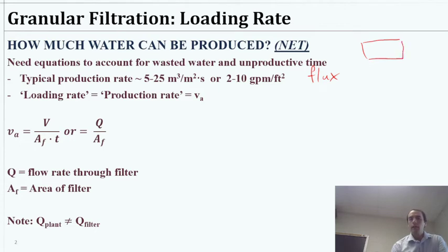So I'll say the plane of the surface of the filter bed. So a two-dimensional plane. We have some water going through, and normally it would be a flow rate, and then we have some area. So essentially this flux is a flow rate divided by area. So if this is area, meaning length times width.